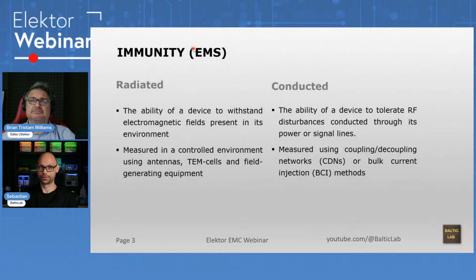There's, of course, also radiated. A great example is when you had your old GSM cell phone too close to the car's radio. You could hear those GSM pulses in your FM receiver. That's a great example of a radiated immunity issue.